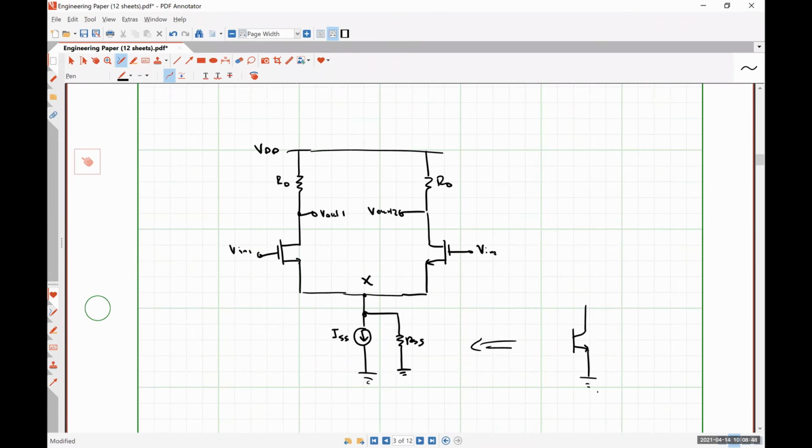We know it has some finite amount of current and some finite amount of resistance, so we are representing that with the Norton equivalent. And this has a fixed voltage of VB3 if this was Q3 or whatever. So for small signal, the current doesn't matter. All we see is a resistance, which means RSS is exactly equal to r03 because it's a current source.